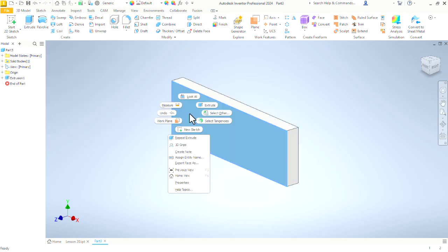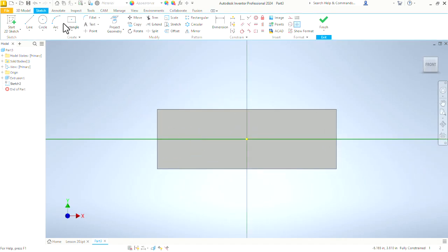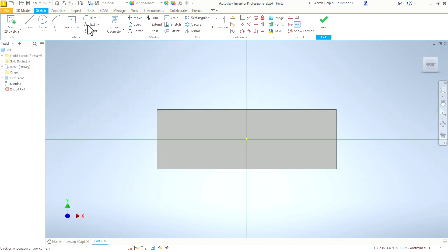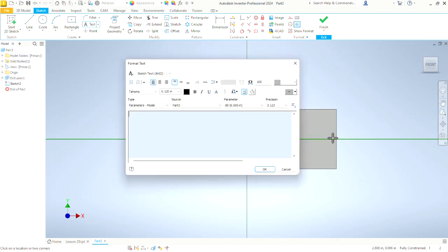Let's make a new sketch on the face of this part. Let's create some text now. We haven't looked at text and using text in an extrusion yet, so we will do that. Click on text, and we need to give it a location. Let's draw a big box that about fills the top half of this part. Exact size is not real critical at this point, but so that everything is centered, let's click the center justification button, and then over here the middle. That gets us centered left to right and gets us in the middle, top to bottom.